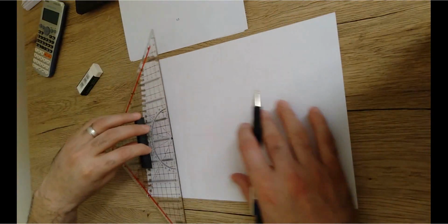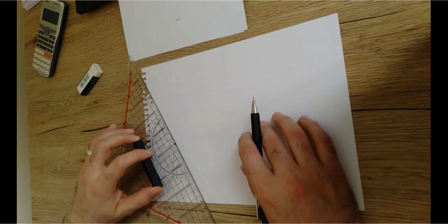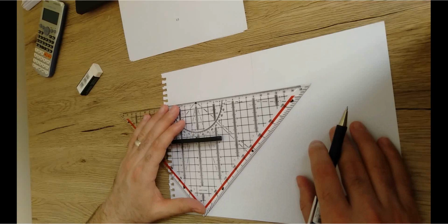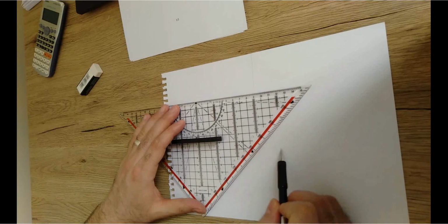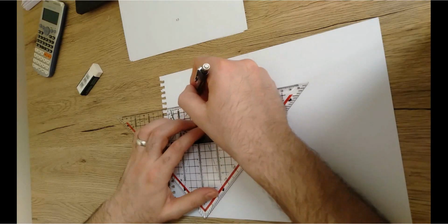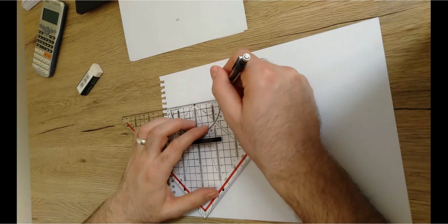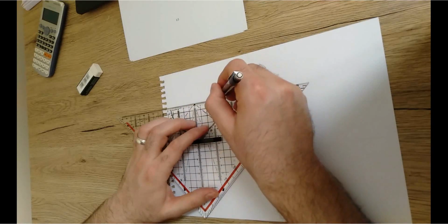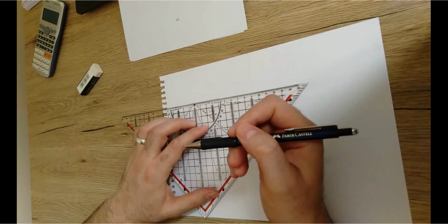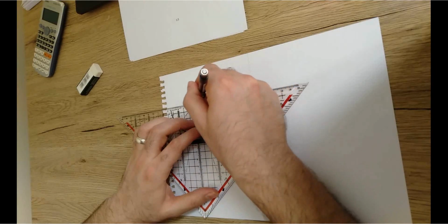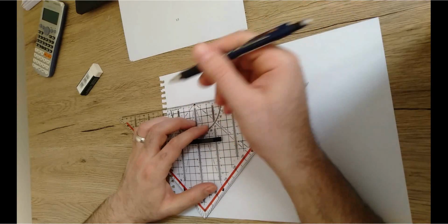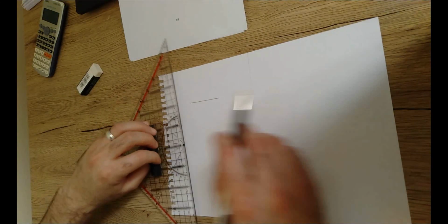Anyway, let us start with example A that is already given there. I'm just going to draw two lines. One is a horizontal line, so I'm going to align this line to the horizontal baseline that I just drew, to make sure I have a truly horizontal line. I'm going to draw a line that should be very light in the beginning, but I'll push a little harder so it can be seen in the video. It is not necessary in the beginning to have a thick or clearly seen line. It is advised to draw everything smoothly in the beginning. So this is the first line.